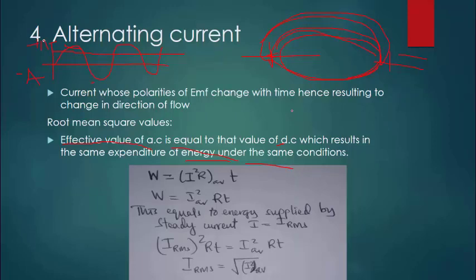So suppose that we have work done is equal to I squared R times T. Anyway, R is a constant, so you can move it outside. So we have an average of various I squares as per variations of the AC as it is varying.